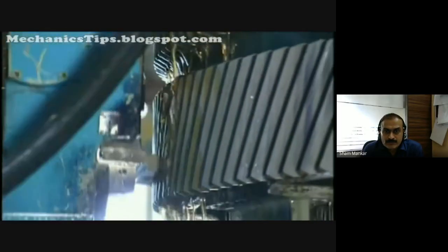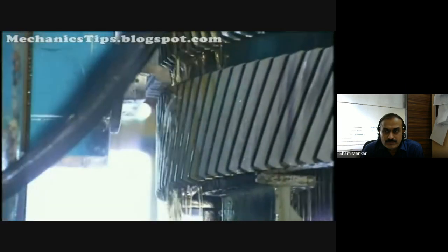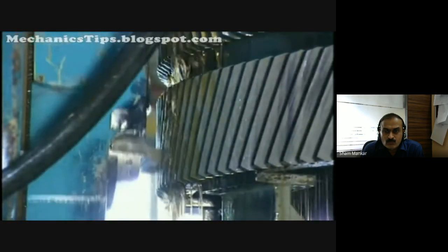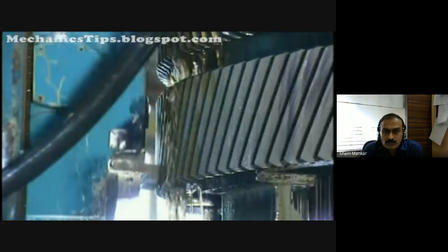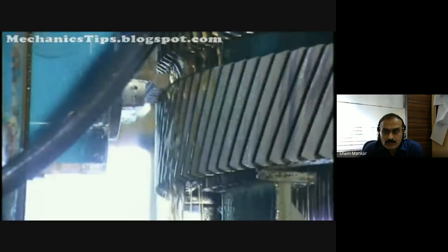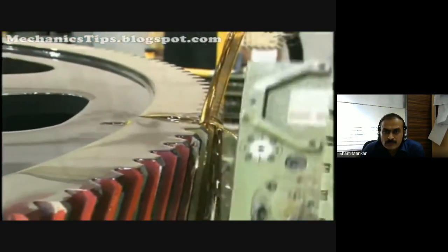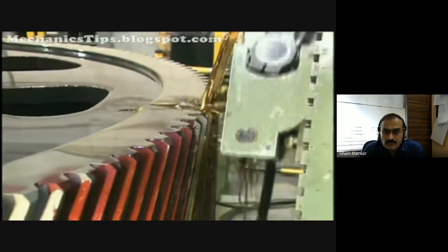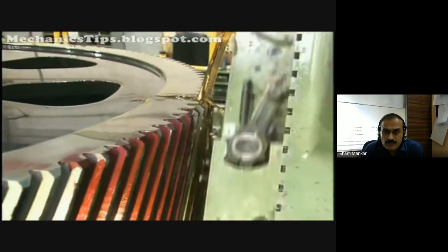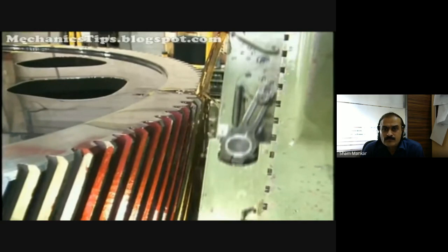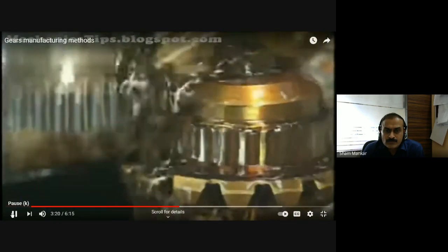Rack-shaped cutters typically have between 6 to 12 teeth that reciprocate into the gear blank. Once the rack cutter finishes a pass, the cutter is disengaged and returns to a starting point to begin cutting again. When shaping with a single point cutter, the cutter reciprocates, making successively deeper cuts until a predetermined depth is reached. Gear shapers are used to make internal gears, shoulder gears,